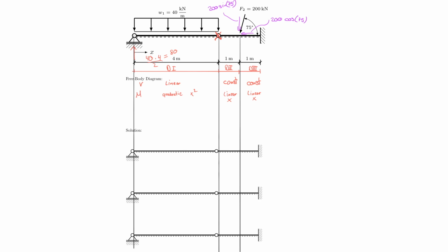All right, so on the left side, I have a roller. Now we're talking about a normal force diagram, and normal force here happens to be in kilonewton. On the left side, I have a roller. That means the normal force cannot be resisted or created, so everything here has to be equal to 0. I'm going to indicate that by a line through there. In that second domain, this very same thing is true. But in the last domain,